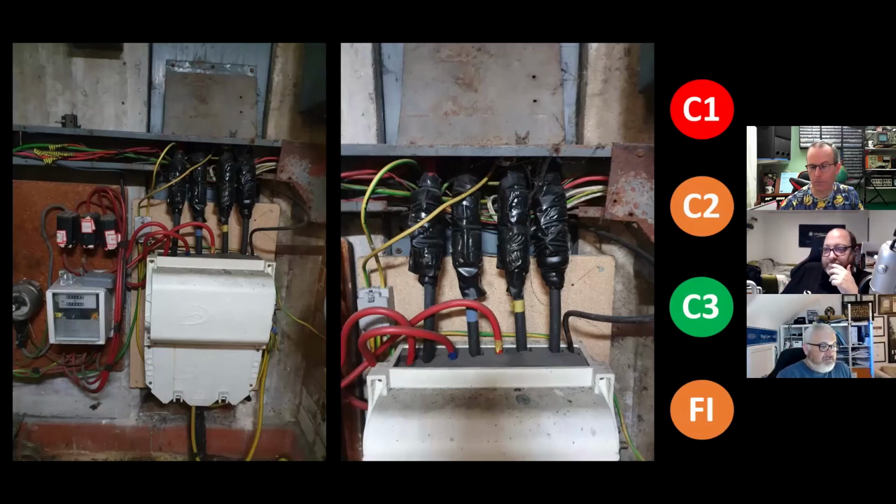You've got a brand new Lucy cutout. Those cutouts have at least 200 to 400 amp supply fuses in them. But we have this lovely, beautifully shite lash-up. That's the only words I can use because, look at it, you've got a three-phase supply coming out here with the red single cores. That's old DNO supply that they've reconnected back into a new intake.